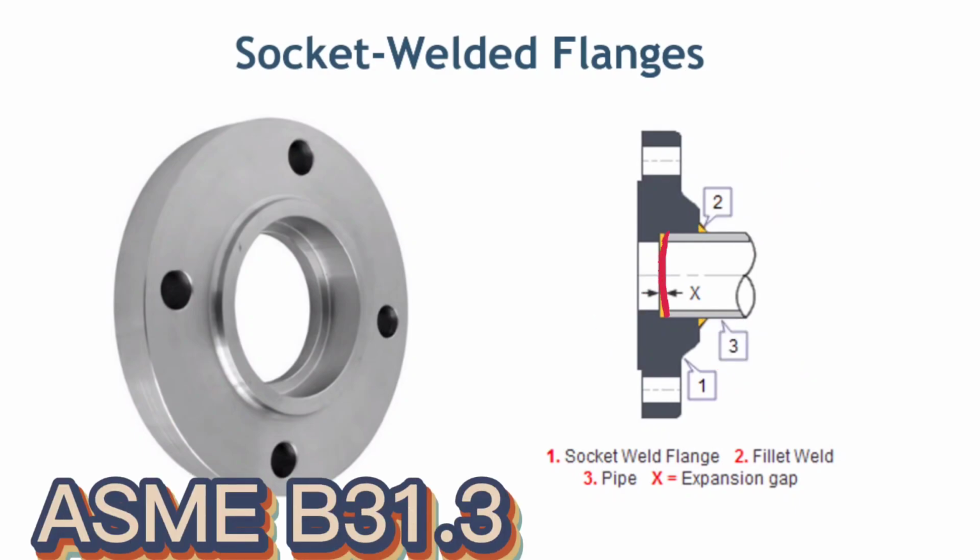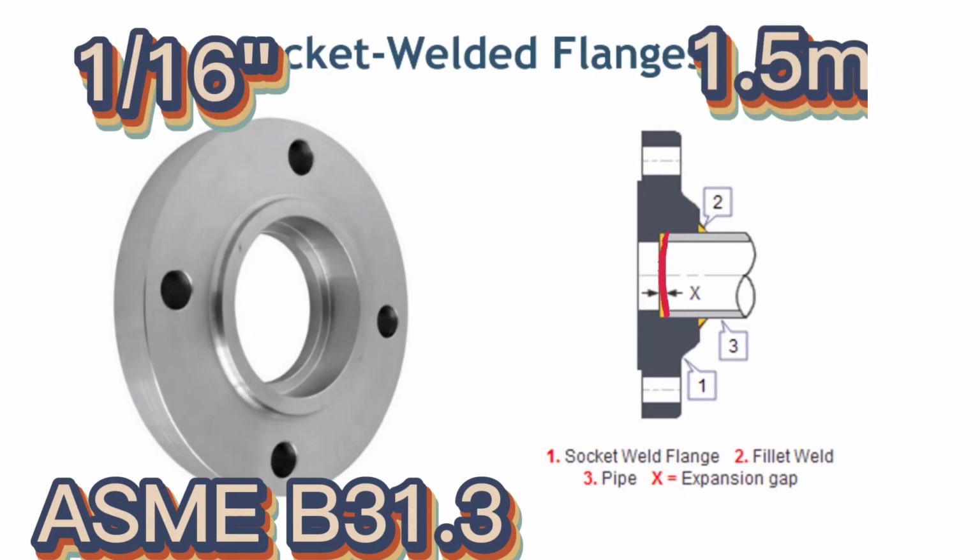The ASME B31.3 standard states that an approximate gap of 1/16 of an inch, 1.5 mm, between the socket and pipe end is required.